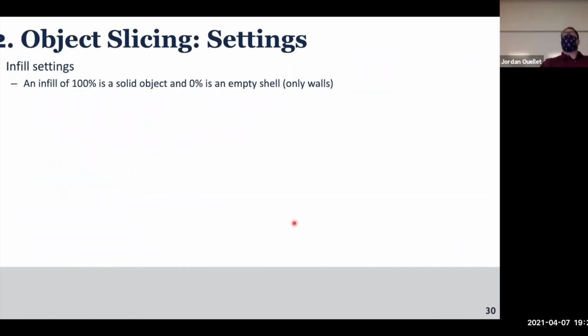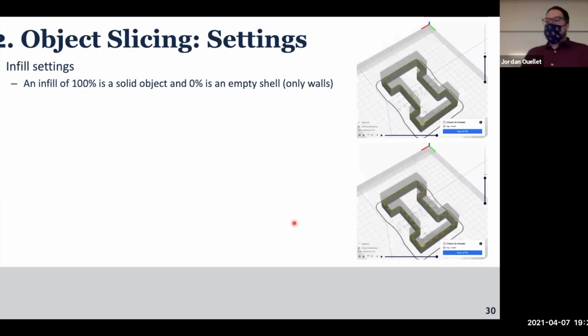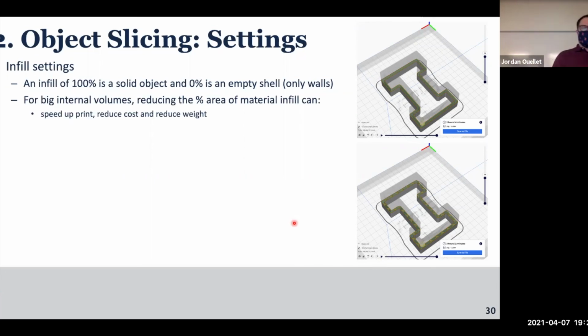What's super important as well, the infill setting. So you can specify 100% to have a solid item. We cannot probably see on the projector maybe. You see this one is this empty shell, 2 hours, 44 minutes, 22 grams. This one, 3 hours, 32, but just 37 grams. So 32 versus 37 grams. You don't use a lot of plastic, but you get a lot more rigidity. It's like a truss design, for example, for a building. By using the right material at the right place, you can improve strength a lot without using much material. So that's what infill is doing.